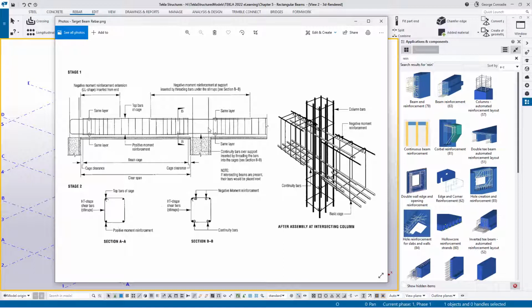in elevation. We have bottom and top bars. We do have a connection around the column where the splice on the bottom is slightly shorter than the splice on the top. And from what I understand, it's your negative bending moment that flows over here. It's where it crosses the zero line. That's really where you want to get the splice, and it's a bit further away from the column.